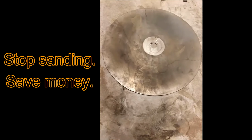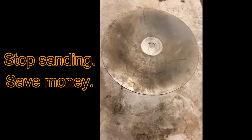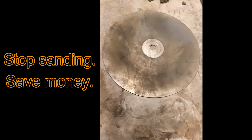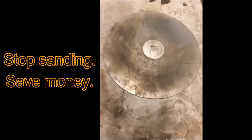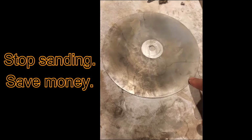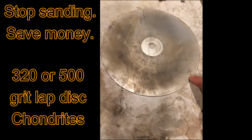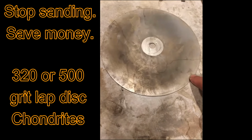What's the grit on the lap? So you can get them in any grit, running from like 180. They make even coarser ones. They make down to 60, which is insanely coarse, all the way up into the thousands. So what I would recommend is, if you want to clean up slices that have cut tabs and stuff like that, I would get either a 320 or a 500, which is a medium kind of grit.